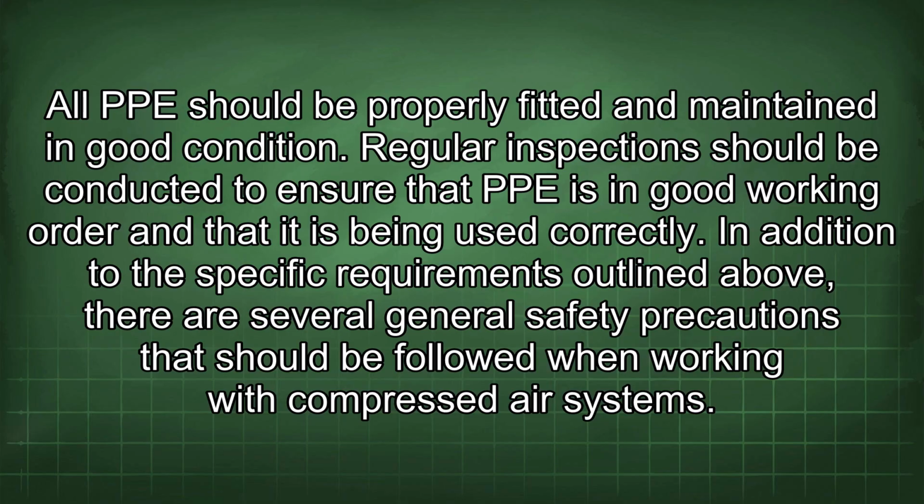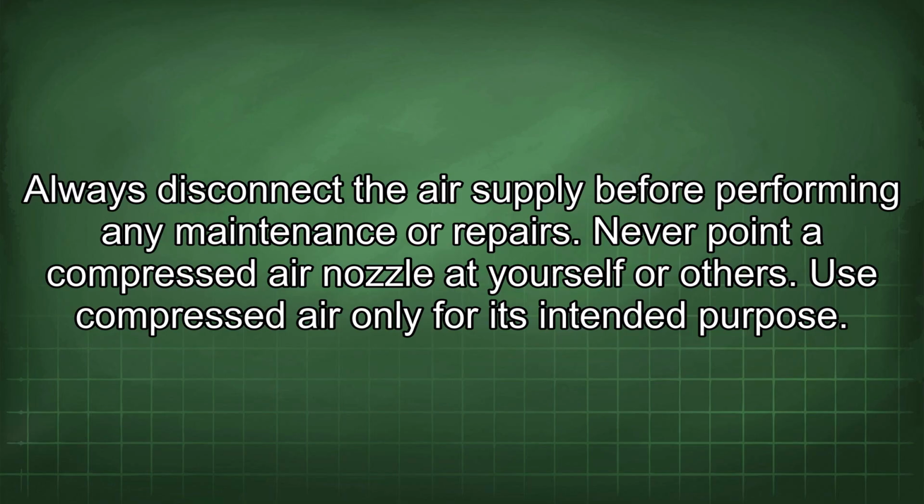Regular inspections should be conducted to ensure that PPE is in good working order and that it is being used correctly. In addition to the specific requirements outlined above, there are several general safety precautions that should be followed when working with compressed air systems. Always disconnect the air supply before performing any maintenance or repairs. Never point a compressed air nozzle at yourself or others. Use compressed air only for its intended purpose.